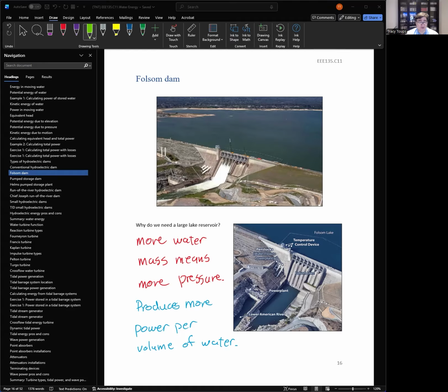Okay. You also have up here these gates. These are overflow gates in case there's too much water. Instead of going to the penstock, you can overflow and bypass the generator, because you don't want to put too much water in the generator. You might overburden it. So just in case we have too much water, like it rained too much or there was too much snow, this is a good bypass feature. You can see right here, they're opening the bypass to let the water through.